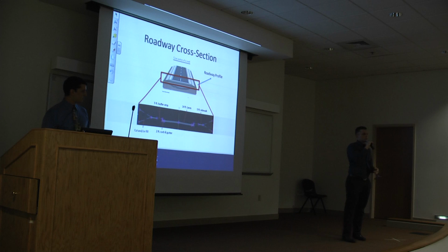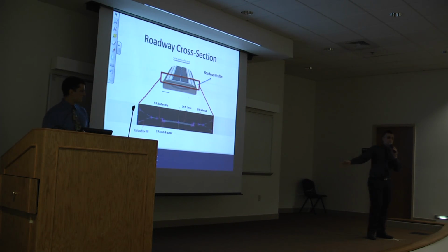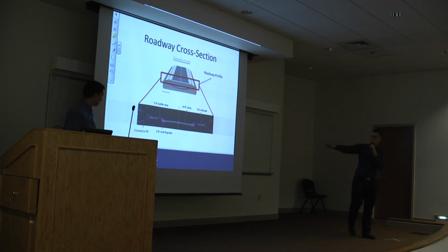Here's a cross section of the roadway. At the top is just an artistic rendering of what we would actually see in the bottom part there. As you can see, we designed 14-foot lanes, and the sidewalks are also there. Also on the sides is just a cut and fill, which is basically bringing dirt in or taking dirt away as needed.